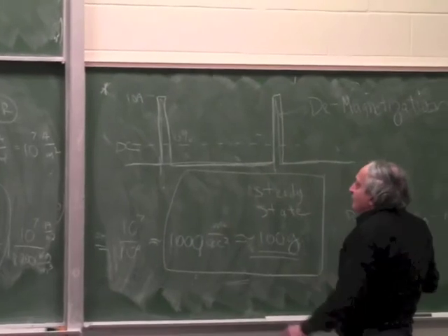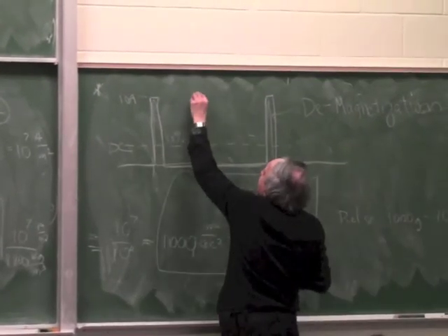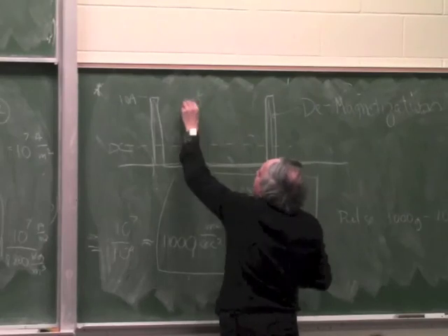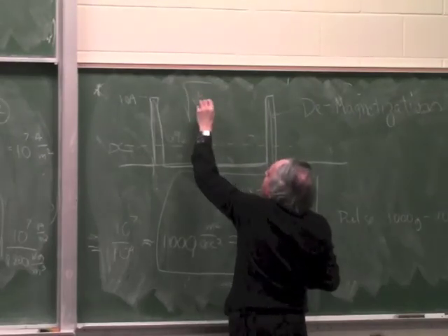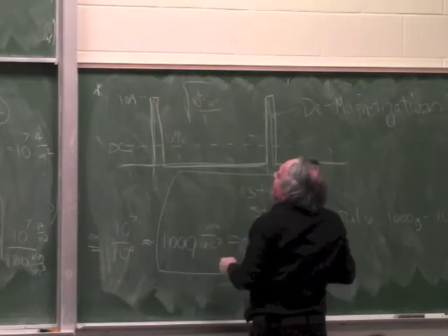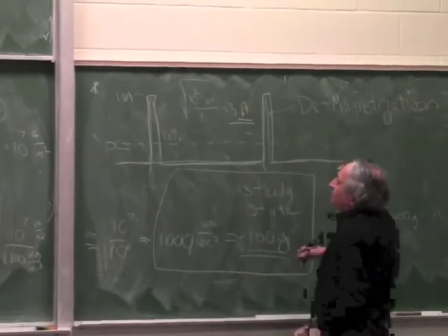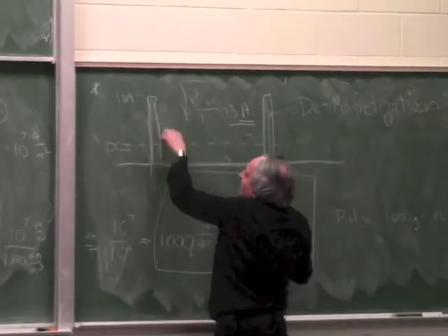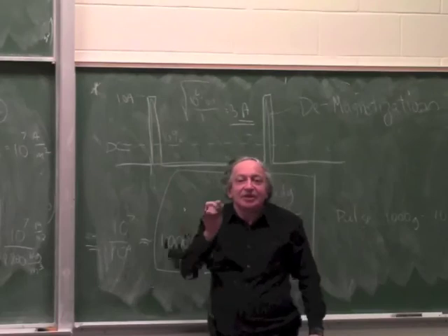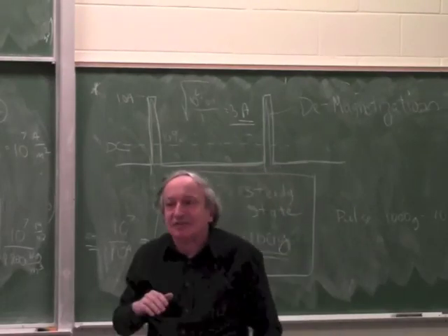So you have to take the RMS, so you take the square root of 10 squared times 0.1 divided by 1, and then you end up with roughly 3 amps. So the equivalent heating of that pulse is like 3 amps, and the narrower the pulse, the bigger the ratio between RMS and average.